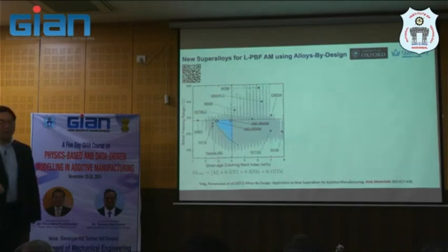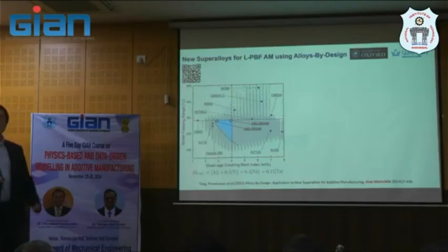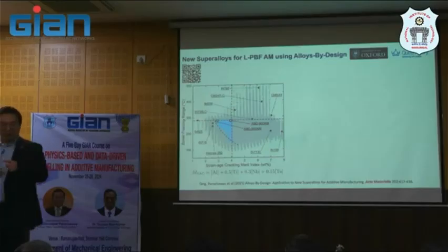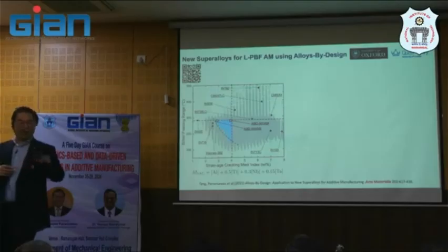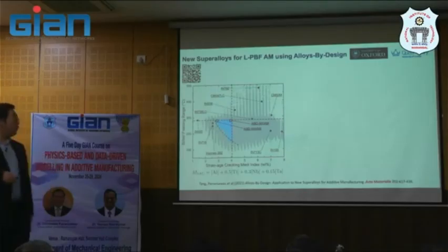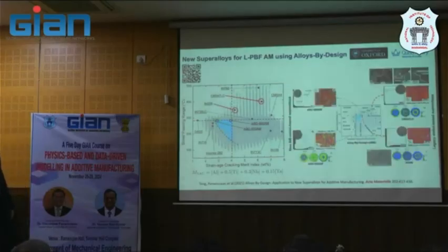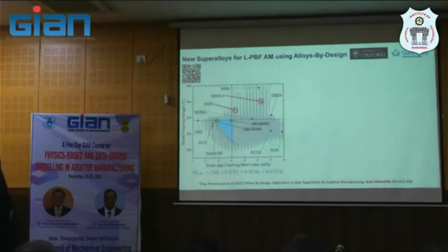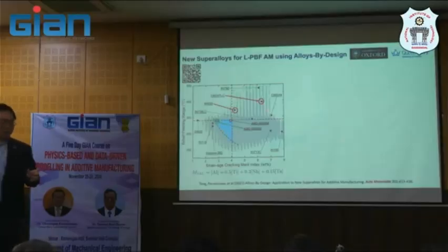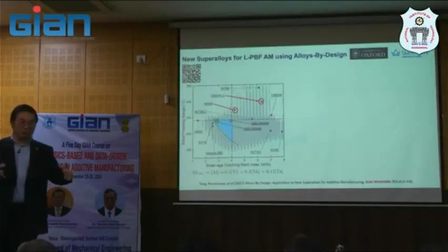If you vary the content of aluminum by 0.01 weight percent, and then you get a combination of the material. Let's say this one varies 0.01, and then another one 0.01, or keep it constant and vary 0.01. What you will get is about 10 million compositions in the range of acceptable nickel-based superalloy, not too much.